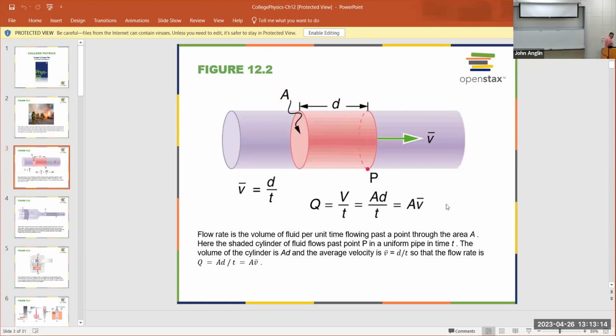Or if one goes down, the other goes up. So in the case of our pressure washer, if we start constricting the hose, if we start making the aperture that the water flows through smaller and smaller, that means our area gets smaller and smaller. So area decreases. But area times velocity has to be Q all the time. So if area goes down, velocity has to go up. So that explains why in our pressure washer, if we make the aperture smaller and smaller, the velocity of the fluid has to increase, which again, we showed with Bernoulli's equation the other day.